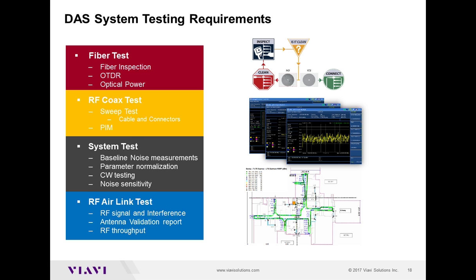It will give you an idea what the expected loss is, and you have to ensure that everything is within those specs, right? So if the power is not being met, then you will have to do troubleshooting. Maybe you'll have to run an OTDR test in that scenario. Maybe you have a visual fault locator for any macro bend or anything like that, right? So those are the solutions that are needed for fiber. So it's like a typical fiber test solution in that case, right?